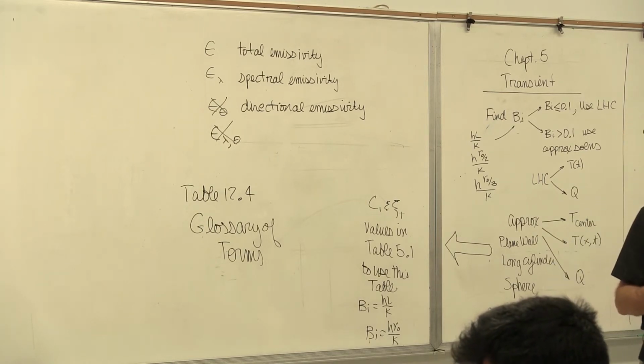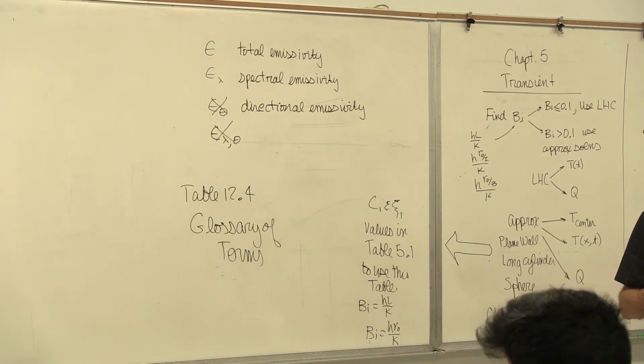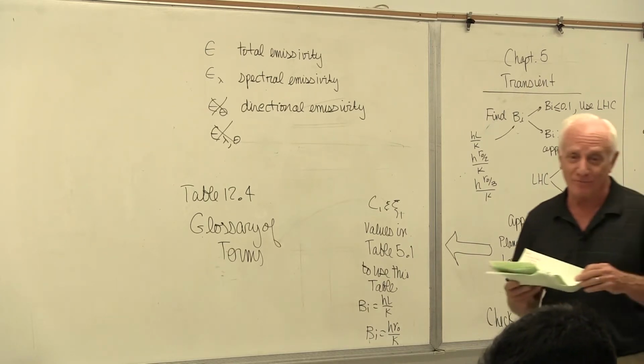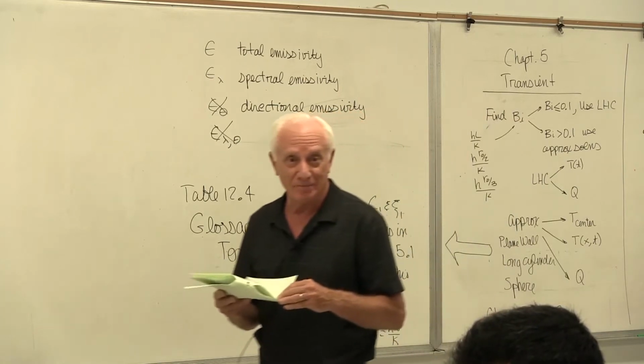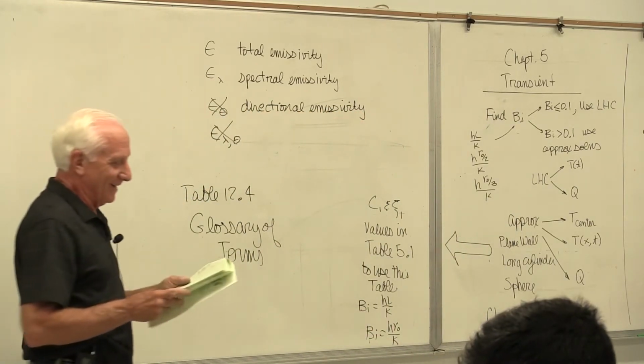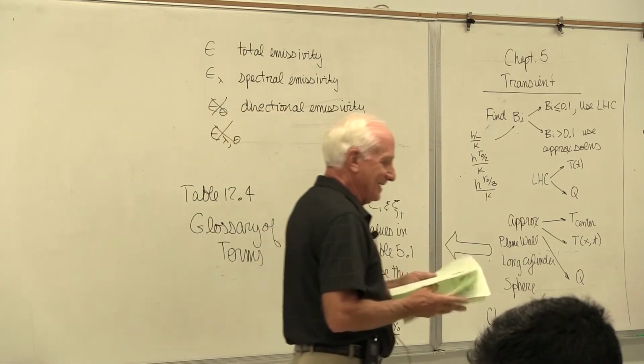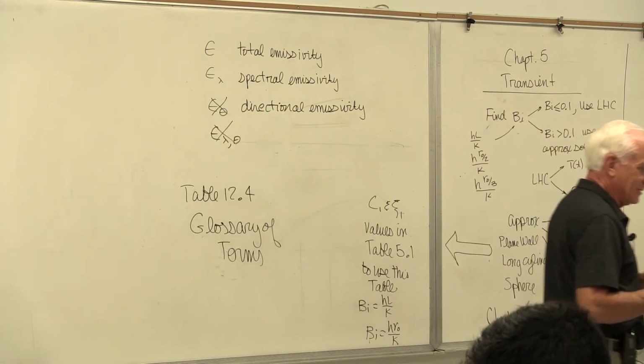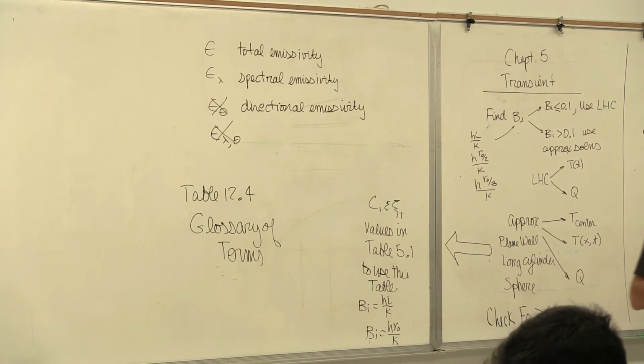Make sure when you get your view factors they're less than 1. Some people got greater than 1. You can't have more energy than 100% transfer. So you know if you're right or wrong if you get 6 on that answer. You misread the graph. The answer is 0.6, not 6.0. 13.9, I set that problem up for you in class, so I won't go over that.